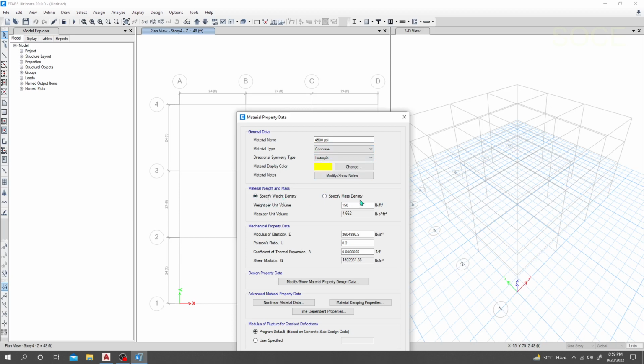From here, a specific unit weight density. So what is actually, they have some issue. So unit weight per unit volume. If you use brick stone, then it will be 135 lb per cubic foot. But if you use stone aggregate as a concrete, or to cast concrete, then we'll use 150. This is very critical. Okay, so I am going to use stone as a concrete, concrete materials, then it will be 150.